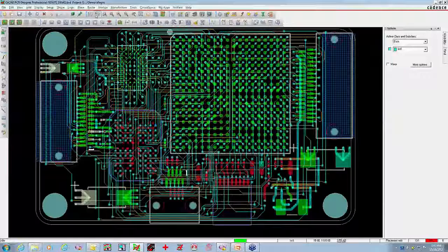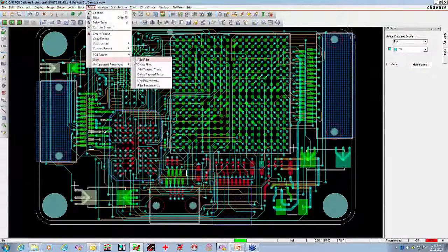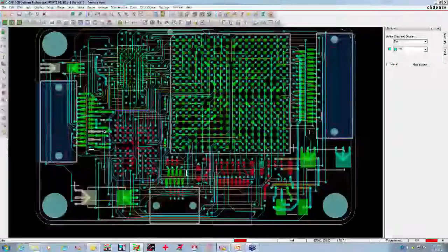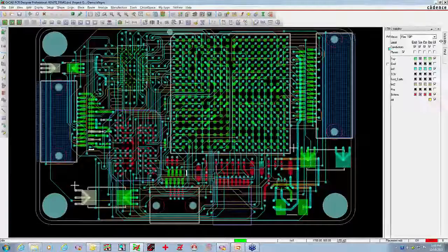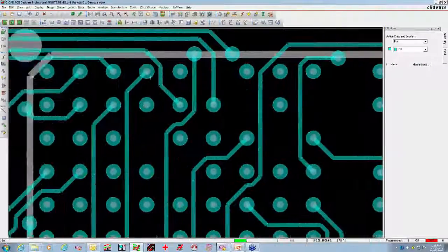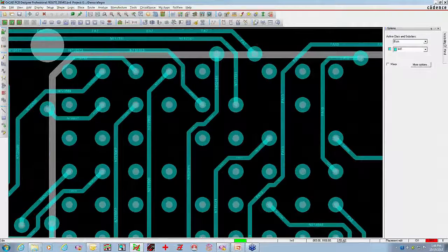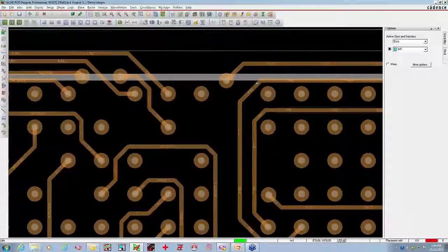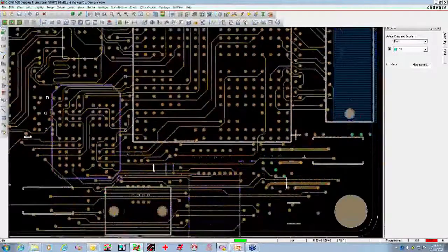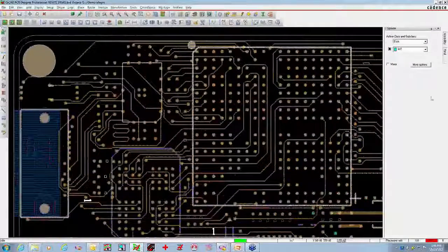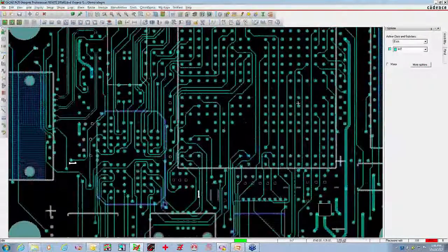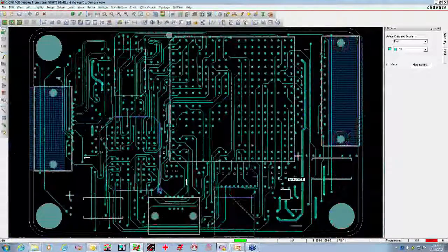So let's go ahead and employ some of my glossing techniques now. If I go to the gloss menu, I'm going to go to my line parameters, and here I can pick and choose those things that I want to try to eliminate. So I'm just going to go ahead and gloss it. It'll do a little bit more optimization. If I go up and look at that layer that we looked at in the router, I think it was up in this area right here. Yeah, I think it was this trace right here. It had the 90-degree corner on it. So you can see by further glossing, I've really optimized and cleaned it up even more. So it looks a little bit more desirable. If I look at the other layer, you can see, again, it looks very clean. So I can achieve a pretty good result.